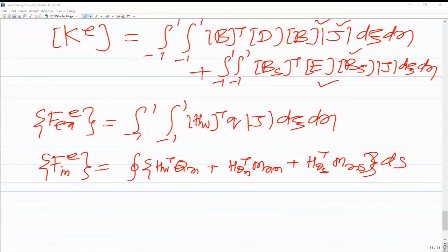I have talked about only two elements, but there are many other elements developed for classical plate bending, such as the assembly of three triangles for a triangular element, and the assembly of 12 triangles for a quadrilateral element. Those are the different types of elements available to satisfy the compatibility condition for classical plate bending elements.